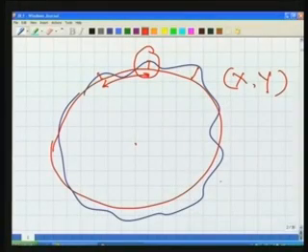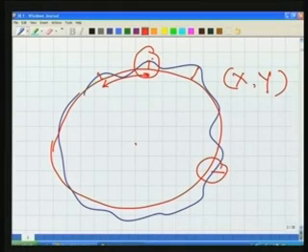So Mount Everest is somewhere in one part of the world, while the Alps are in another part of the world. So in order to compare these two, we need one single reference which is passing through both of them, and then only we can compare the elevations or the heights of these two. So for this purpose, we need one reference system. Well, we are talking that our reference system is ellipsoidal here, and any distance that we are measuring between point A and, for example, point B here is the distance along the curvature.